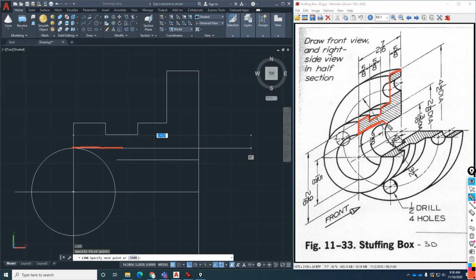And then I'm going to draw that 45-degree angle down to this line. This line is the 1 3/16 that I just drew across this way. So then essentially, this is the shape I'm going to eventually revolve. And once I revolve it, notice I'm going to get everything. Of course, the trick to it would be I'm going to revolve around this axis. That's going to be the trick that I'm going to use in this case.